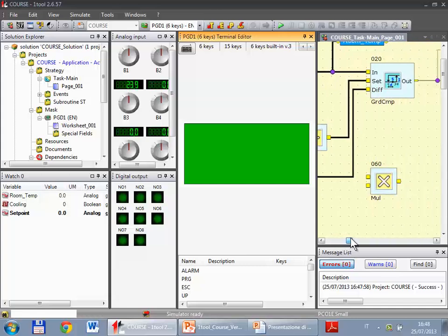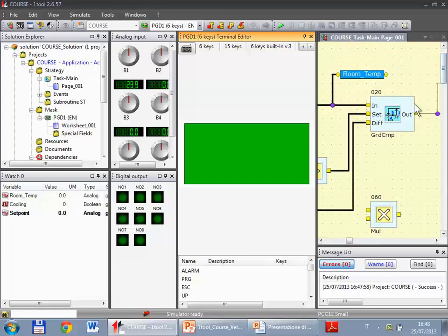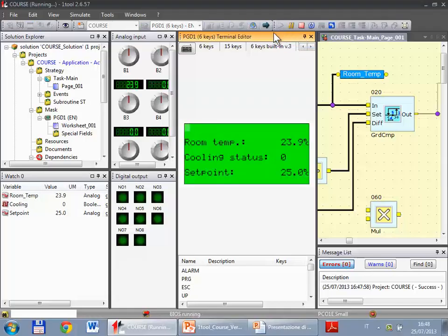Let's locate the part regarding the stage start. I told you that with a set point of 20 degrees, we expect that the block receives 22.5 and 0.5. Let's check. In this case, I prefer to change the set point using the watch list.